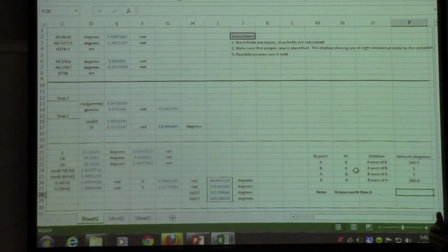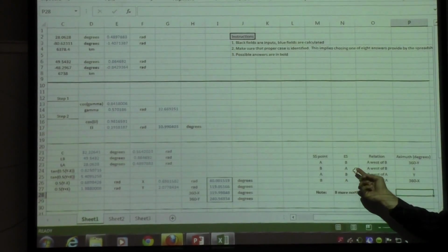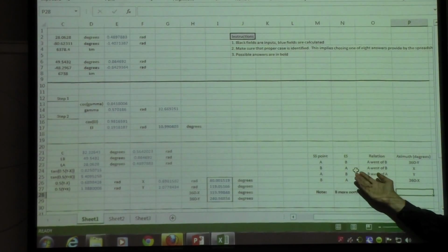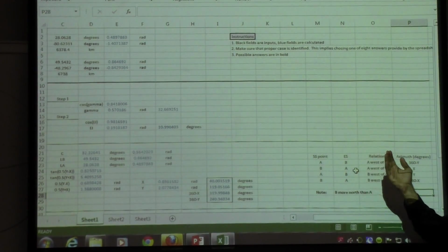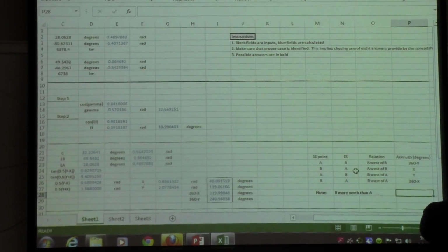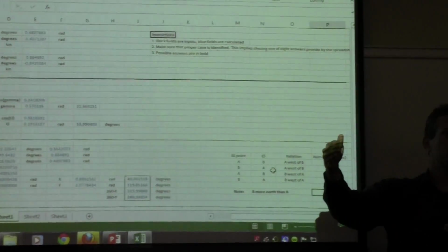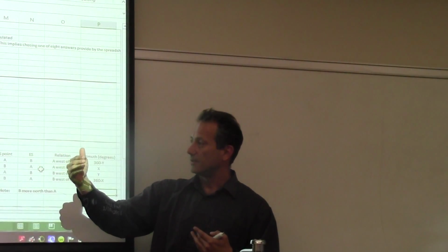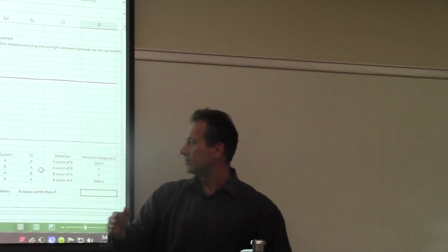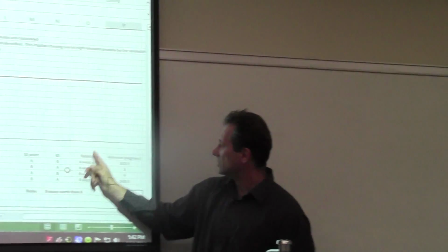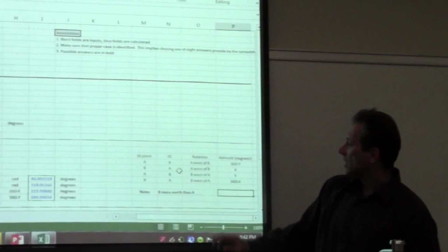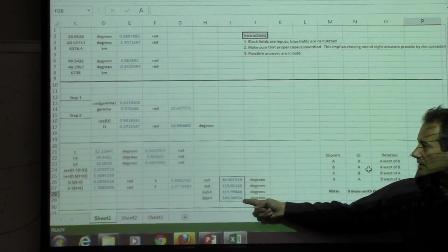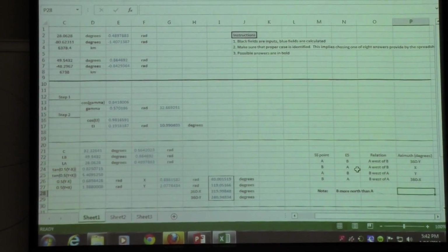Once you know the hemisphere, you have to determine which of these 4 cases you are working with. These cases differ by the points where your Earth station and your subsatellite point are, and also which one is west of the other, right? So you have to match that based on these calculations here. This will determine which of these 4 angles being calculated here is essentially your azimuth.